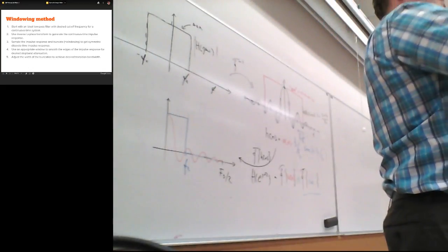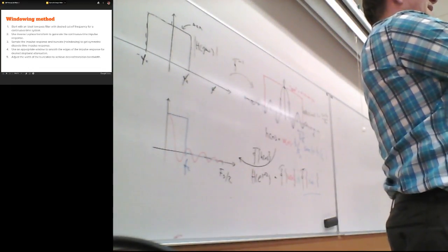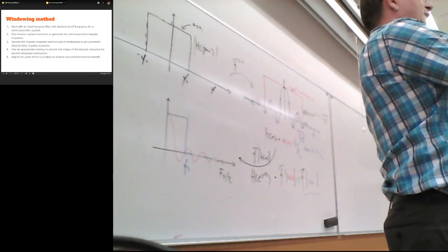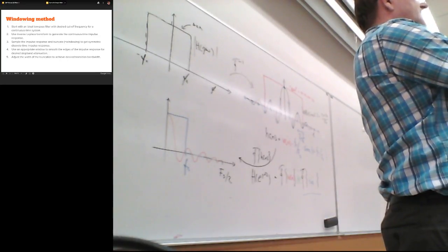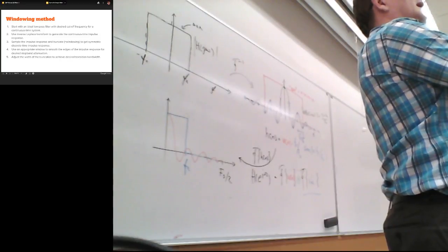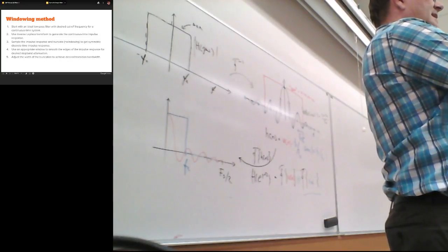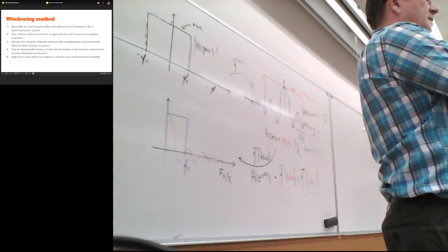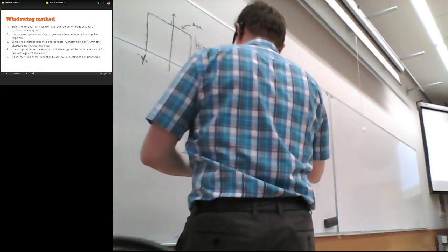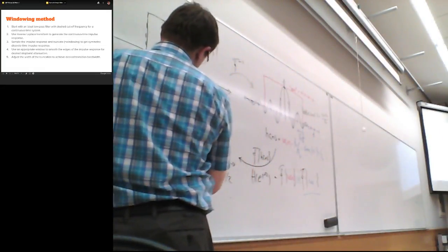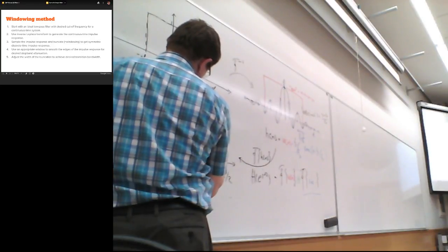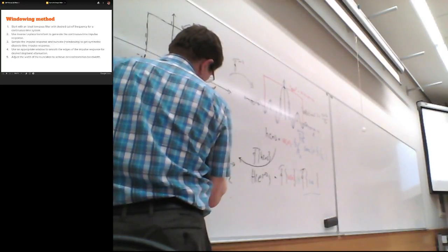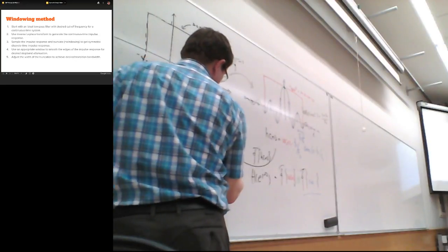So you have two signals, and you basically slide or multiply each of these values like that, and calculate the sum of those products, and then you shift to next time shift and so on. So what happens here, due to the convolution, you will get actually a picture something like this.